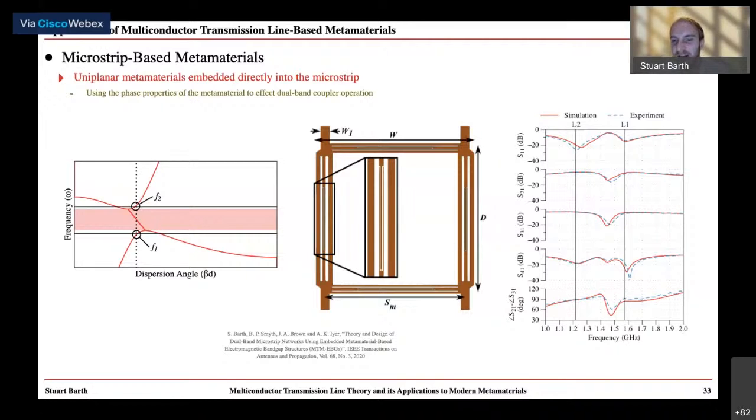So this becomes increasingly incorrect as losses of the system increase, like ohmic losses of the metals. Generally, it's considered that the theory is only valid up to past infrared frequencies, so you wouldn't really be able to use these modes at optical frequencies. Metals are just too lossy. But essentially anywhere below there, wherever transmission line theory can be validly applied, any of these concepts can be applied.